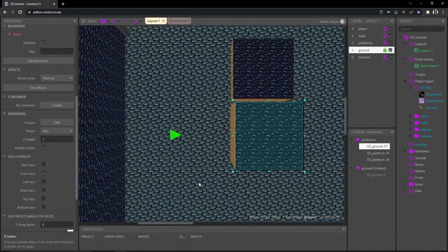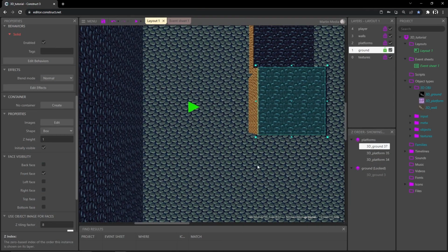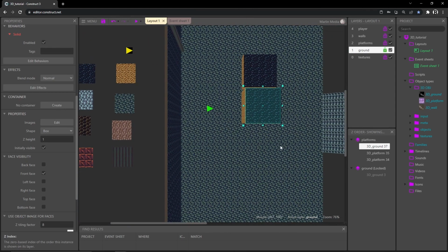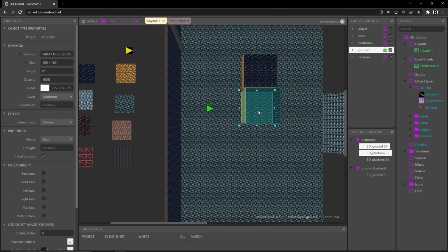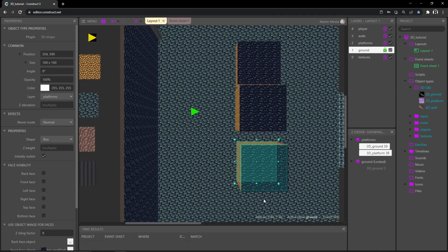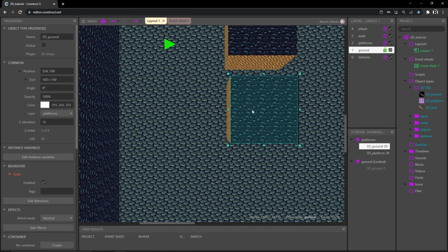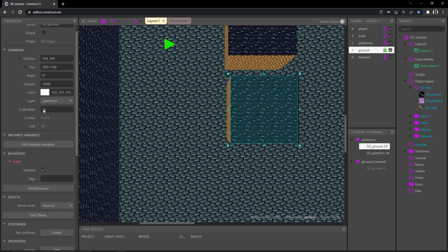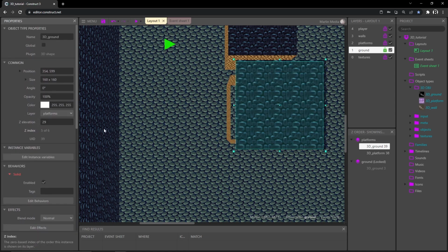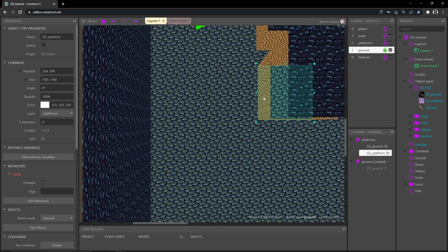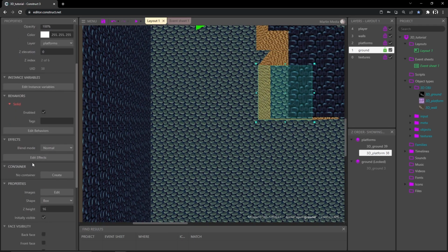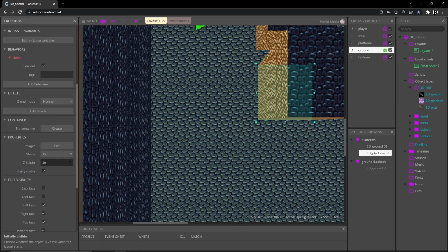Okay, I'm going to exit out of that, and I'll do one more thing here. I'm going to zoom out and draw a selection over our newest platform. Control, click, drag out a copy of those, and then I'll do the same thing here. Click on the 3D ground. I want to go up another 8 units to 24. Actually, let's make it 30. So subtracting its Z height, that would be 29. And then we can click on our 3D platform object and change its height to 30.